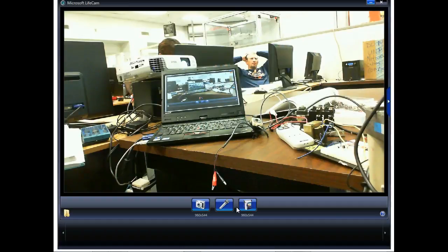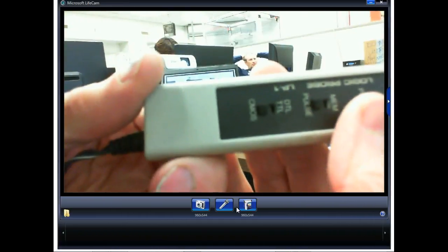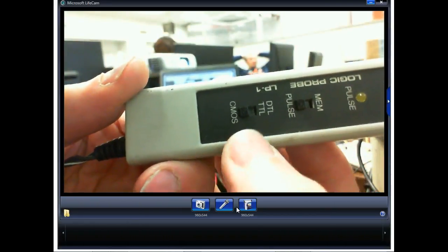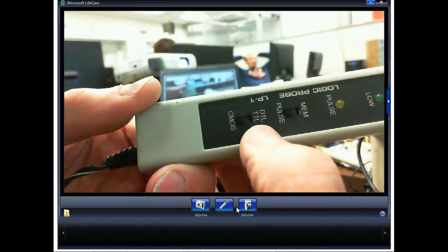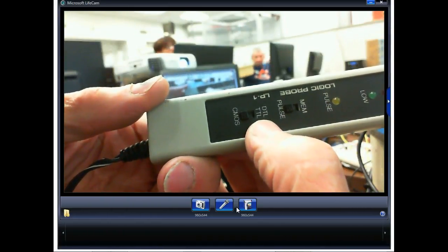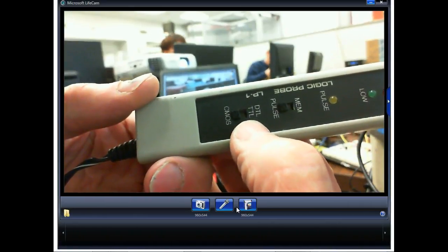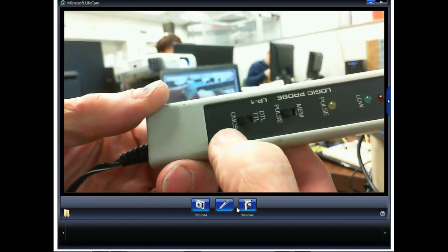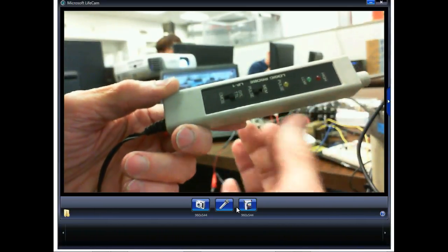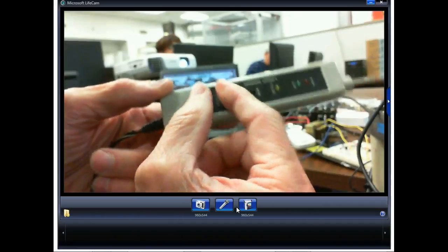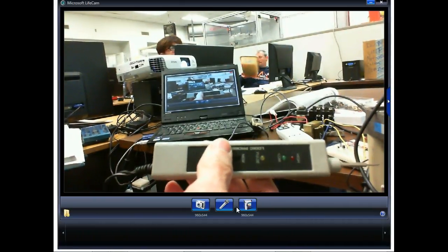We have two types of logic out there. And when you get your probe, if this thing will focus in, notice it says DTL. This is an old one. This is diode transistor logic. You're not going to run that. We just looked at diode transistor logic, right? And then TTL. And then another type of logic called CMOS. So we're going to be working primarily with TTL. So we'll make sure this is on TTL because that's what the probe uses to determine what's a legal high and what's a legal low.